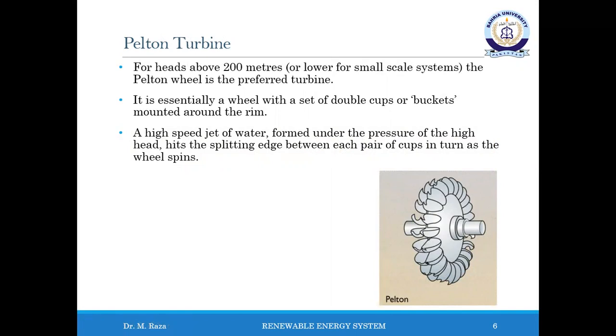Also, the Turgo turbine is based on the Pelton turbine. The Turgo differs only in the angle at which the jet strikes the runner plane, which is about 20 degrees. Therefore, water can enter at one side of the runner and exit on the other side. So the flow rate is not limited by the discharge fluid interfering with the incoming jet as in the Pelton turbine.